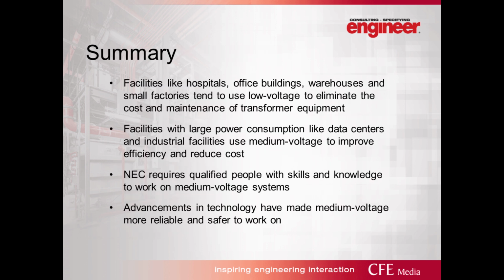So in summary, when you look at facilities like hospitals, office buildings, warehouses, any small facility that doesn't have a large load, they tend to use the low voltage side systems, and this eliminates that cost and maintenance of transformer equipment. I did have an example not too long ago where a client did not want to have medium voltage. They did not want to own or maintain the transformer equipment. So we actually had 6 utility transformers outside the building, serving the building at low voltage. It's all a preference of what you want to have as far as maintenance.